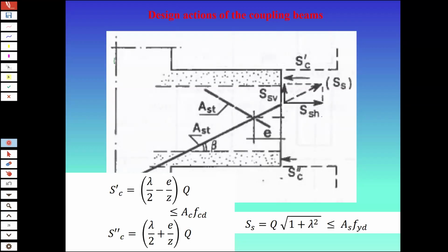Generally, if you look around in most of the common cases when you have to build a fire escape staircase outside of the building, you use these trusses. And they are hyperstatic structures, because when you put a crosswind like this, it's statically redundant. But we design them with a statically determinate scheme, neglecting all the compressed diagonals, because the compressed diagonal can buckle.